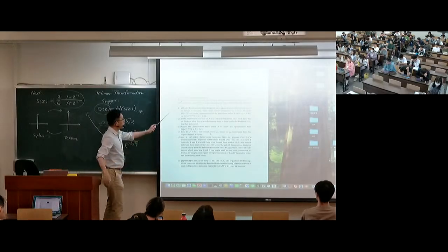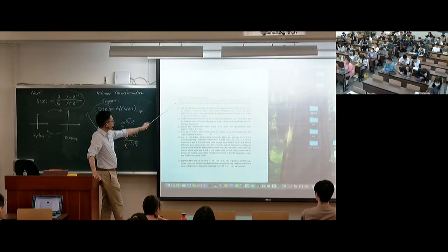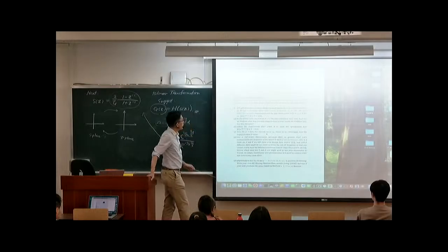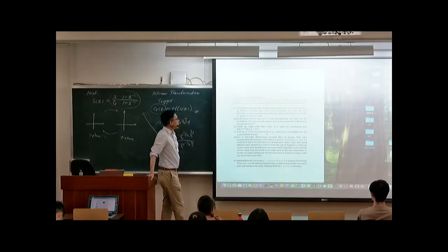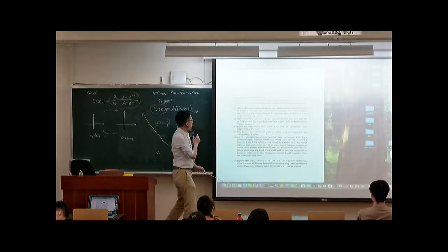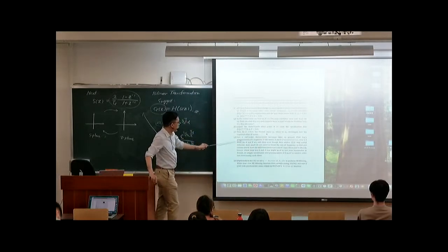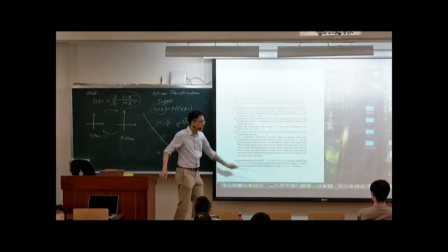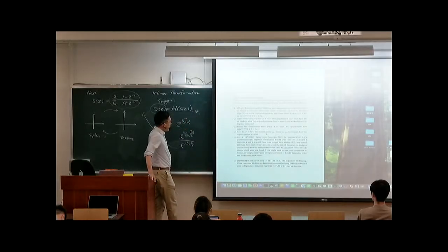In this homework, I'm going to ask you to turn in a short report, limited to 2 pages, and we are going to design a filter, try a few things, changing the corner frequency and the order N so that using A of Z and B of Z, we can low pass our signal. Finally, in the last part, I suggest using a 16th order Butterworth low pass filter to process this file. And I'm curious, what's your opinion? Do you think S and F are still clear even though the timbre might sound different?